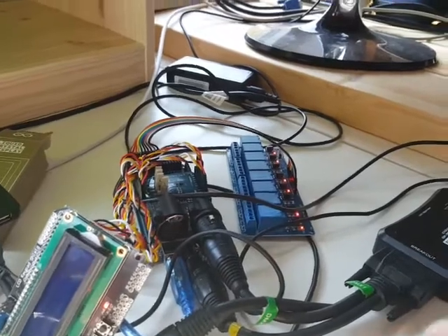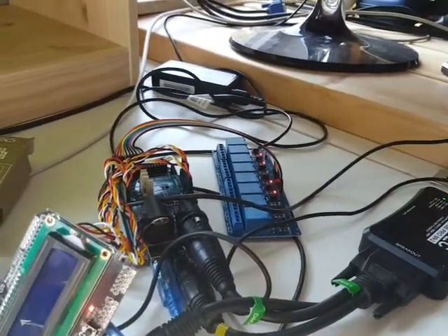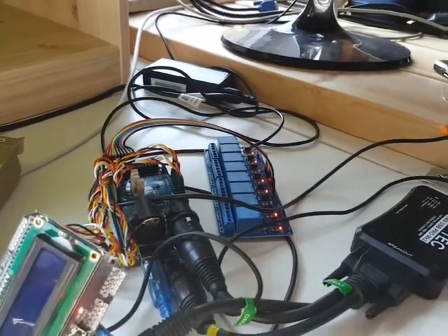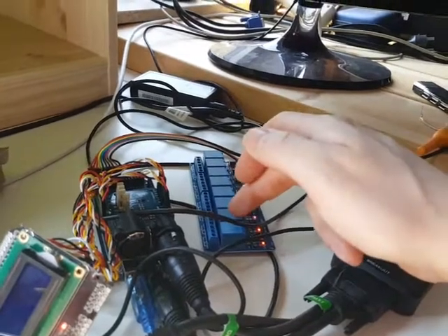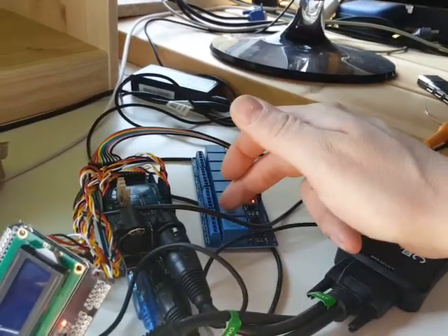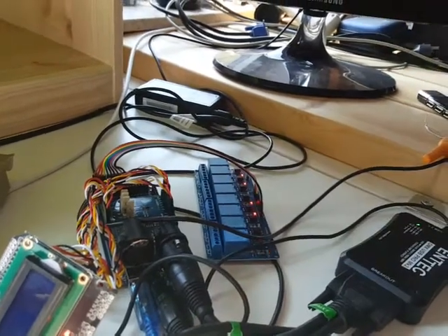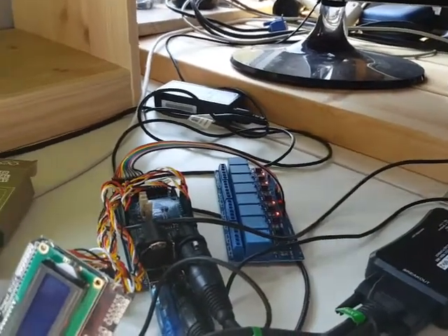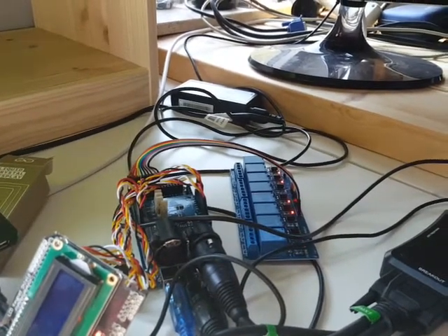Now I can program them in my shell, and I have 2 additional outputs. I had 8 relays and am just using 6, so I added 2 DMX channels. When one of these channels is just over 50%, the relay will be closed, and when it's below 50%, it will be open again.